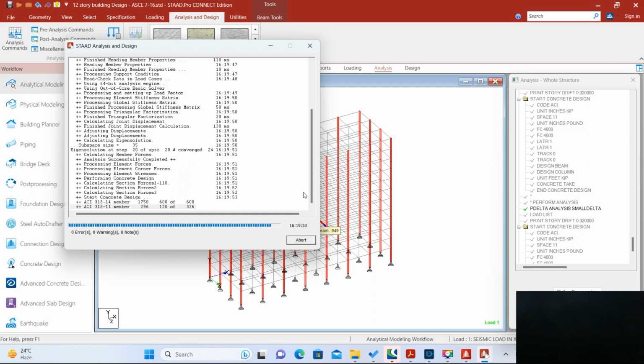And in seismic regions, especially like in Islamabad or Karachi, these cities, or Peshawar and Quetta, these cities are in high seismic zones, and we cannot afford to have thin columns. We should tell our architects that, for God's sake, do not consider to have thin columns.